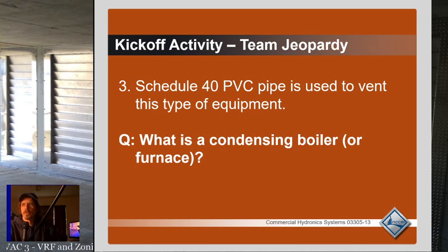High efficiency boilers or furnaces, obviously, if you guys don't know, you vent with PVC because the flue temperatures are so low, because we're extracting more of the heat out. So you've got 80% equipment, which is always metal pipe, right? And 80% and less you can do in galvanized.